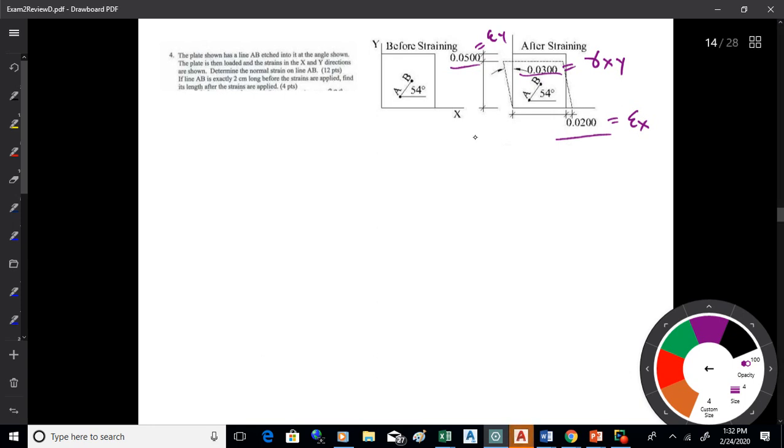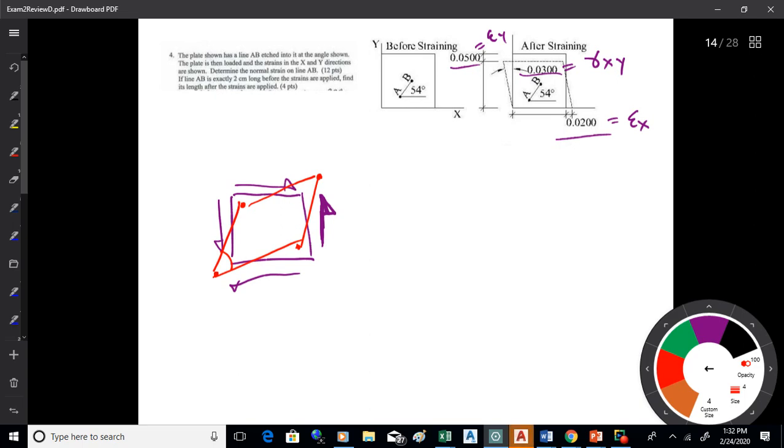The reason is, if you go back to stress, if you've got positive shear stress on the XY plane, your shear pattern will pull these corners out and push these in. So positive shear stress makes that lower left-hand angle less. That's where that comes from.